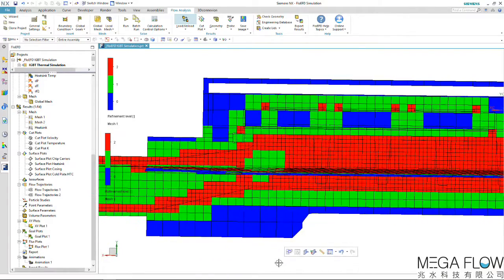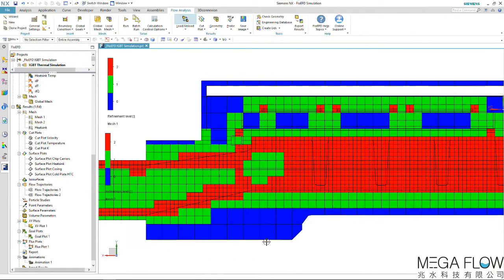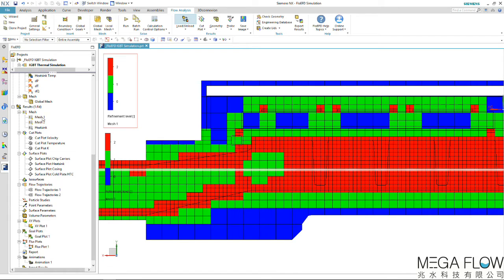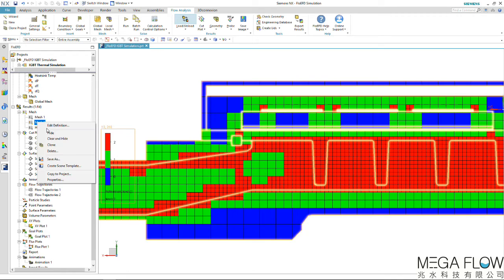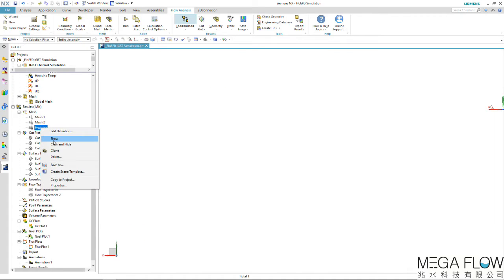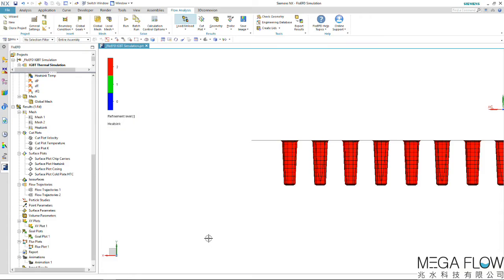The smart cells are always found at the interface between fluid and solid. This is where the boundary layer forms and the convective heat transfer occurs. Smart cells can have multiple control volumes, up to 12 in a single cell. It's this technology which makes FloEFD meshes easy to generate and tolerant of dirty CAD geometry.